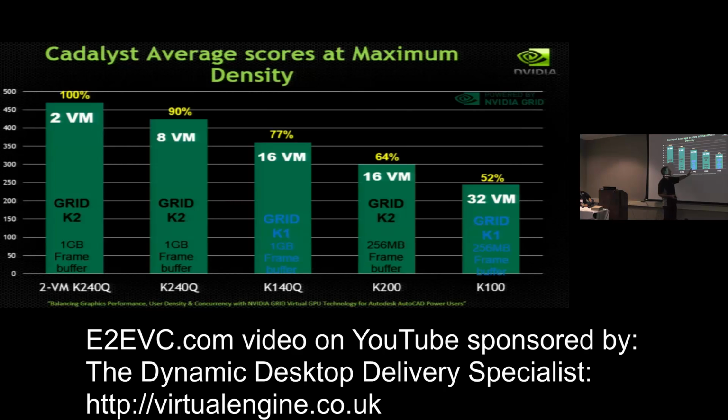When you start getting out into these higher numbers, you'll have to go to smaller frame buffers, and that adversely affects performance too. So you'll see that 16 VMs at 1 gigabyte frame buffers versus 16 VMs at a 1/4 gigabyte frame buffer, the performance drops measurably just from going to the smaller frame buffer. So with AutoCAD, at least, you can see how the performance drops as you start to try to squeeze more users onto the GPU.